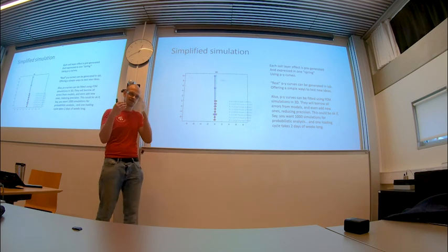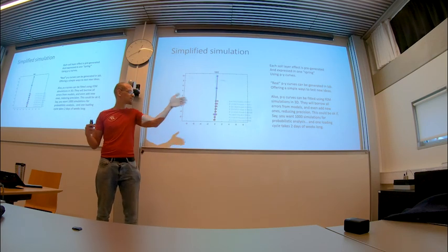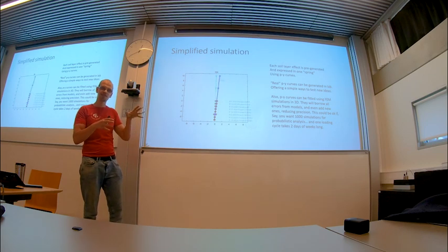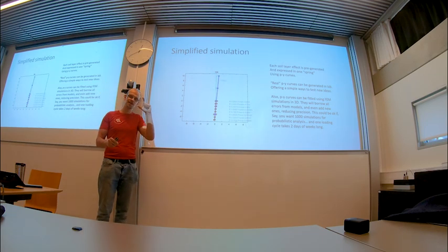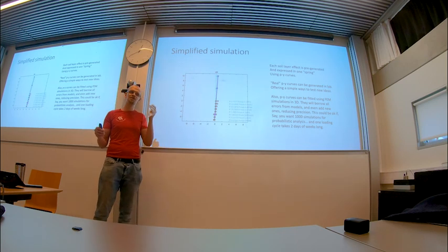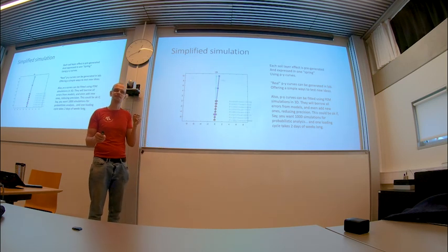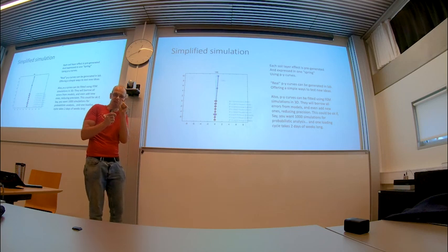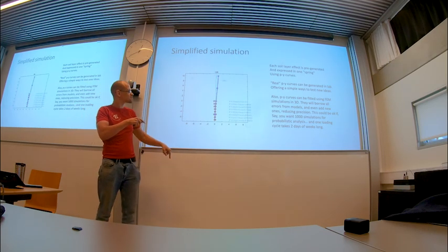So there are impact loads, there are cycles of small amplitude, big amplitude. I started modeling them on a triaxial test on a specimen, and I then tested it on a small foundation. I observed these behaviors, and they were really complicated to describe in small elements, 3D mesh. So I did it with small springs instead.